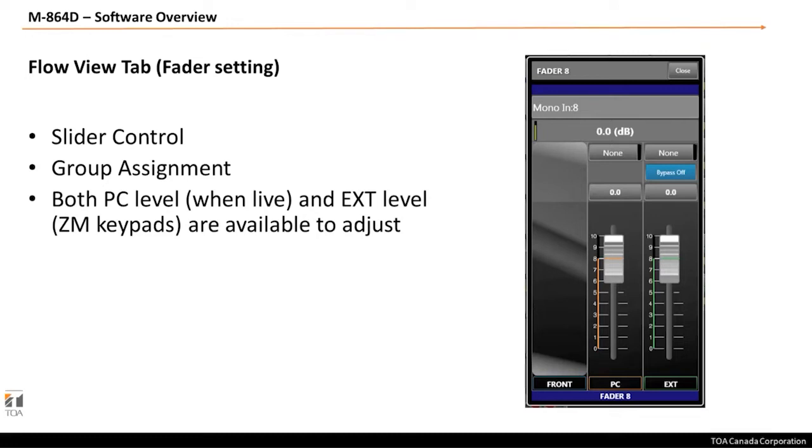So as there are some sliders on the physical mixers, the software is also emulating the sliders. So that's where I was saying that it's important to keep in mind that they're non-motorized sliders. So if you do change some settings from the sliders, and those adjustments are live, instantaneous from the software, it will not change the setting on the device itself.